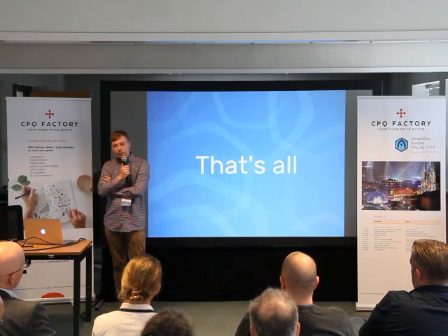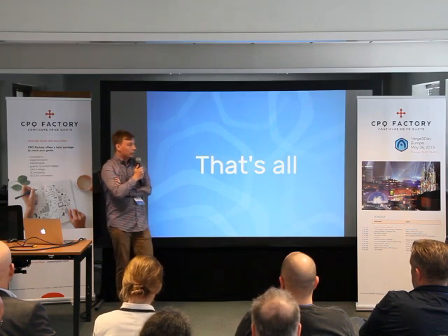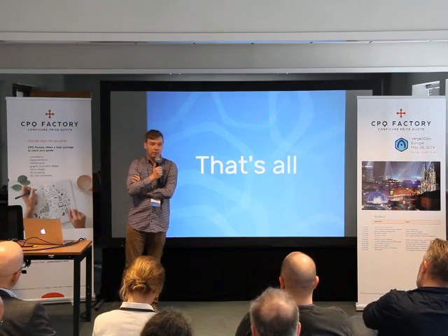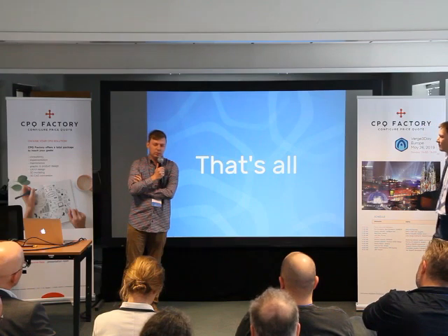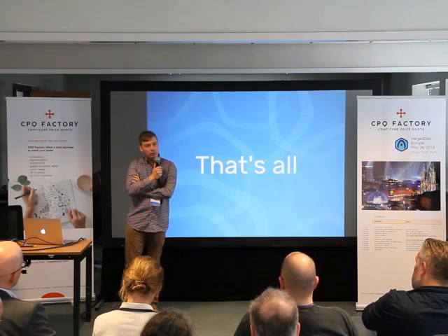But if you leave this object without any baking, for example, on the scooter, if I left this triangulated, you will see not a good result, in fact. Better to use quads for a high glossy object.